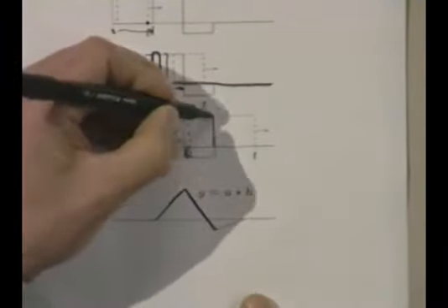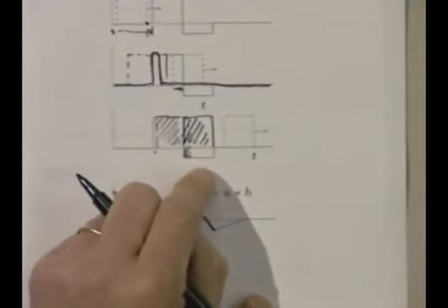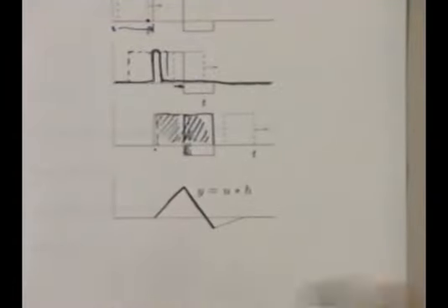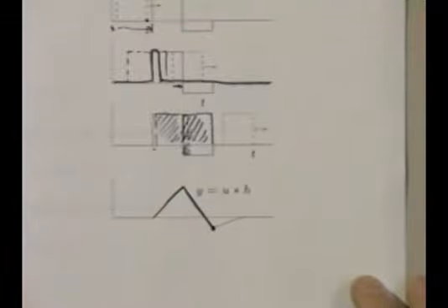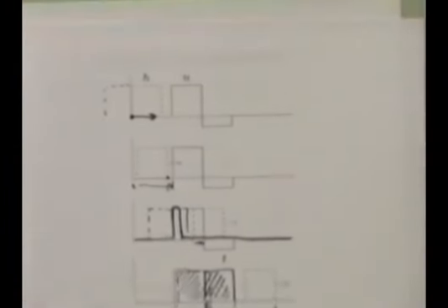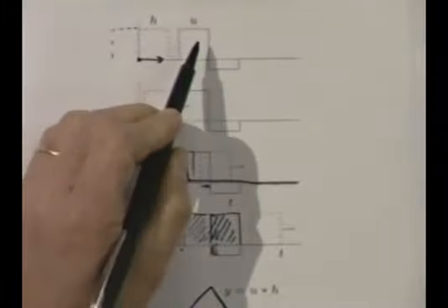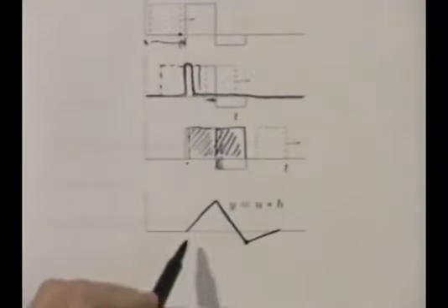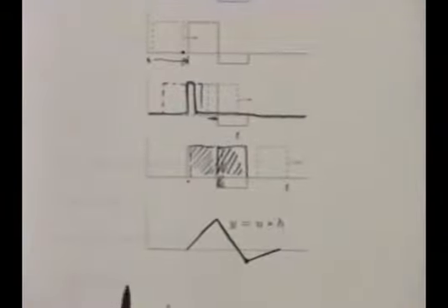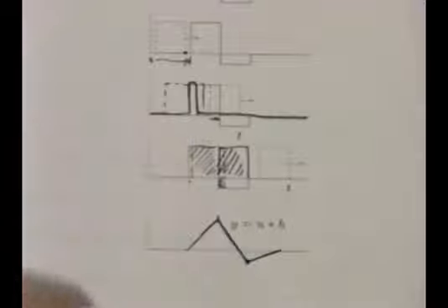And when this thing lines up like that, so that this little thing catches only this negative part, that's where the convolution achieves its negative minimum. And that's this value right here. Then as I keep pulling, I integrate less and less of the negative part, and I get this. So this is a quick way to understand how you convolve this with this to get this. If I put numbers in here, you should actually be able to identify the slopes, identify this, and so on.